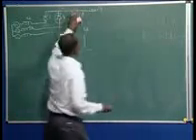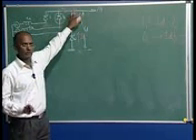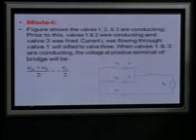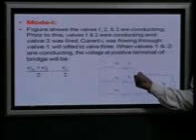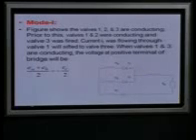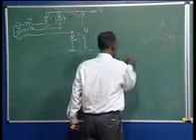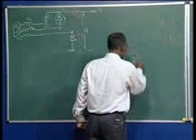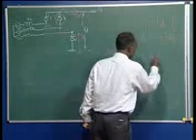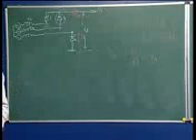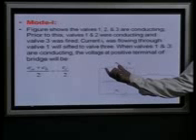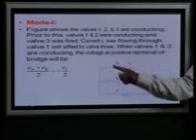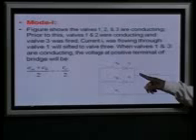Let us see any voltage VA here, and I am going to prove this VA will be nothing but the average of these two voltages. Because there are some inductances here, I can write, let us suppose voltage A here, VA means EA minus L di1 over dt. I can write the current which is flowing here, I1, with this voltage minus the inductance drop L di1, because I1 is flowing here, that voltage will be here.